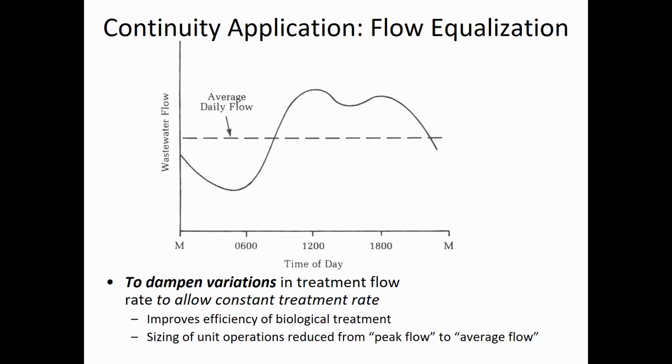If we're trying to always have the average daily flow go into the treatment system, then anytime the given flow rate for a certain time period is greater than the average, you'd take any extra and you'd fill the storage tank. And then at night, you'd drain the storage tank. And over a 24-hour cycle, the objective would be to discharge into the treatment plant at night all of the stuff that you'd stored during the day.